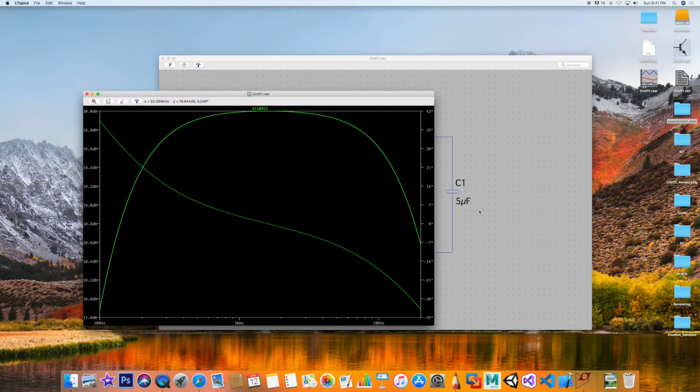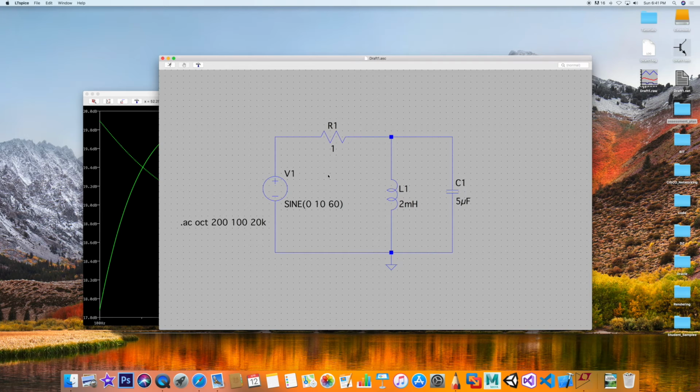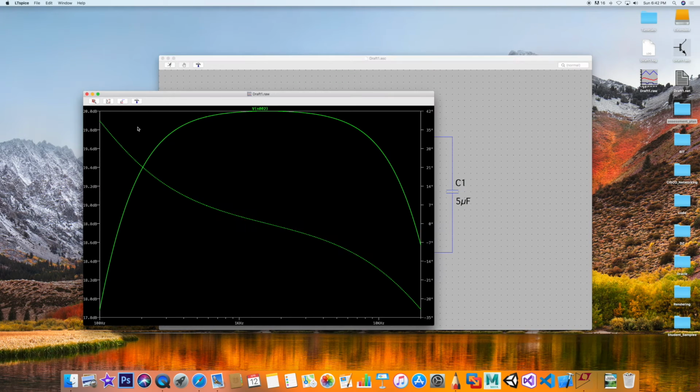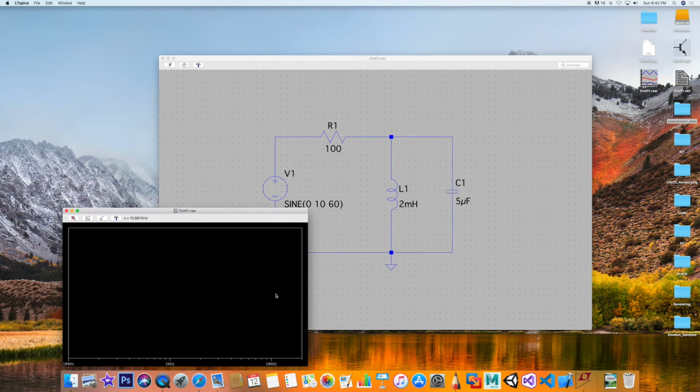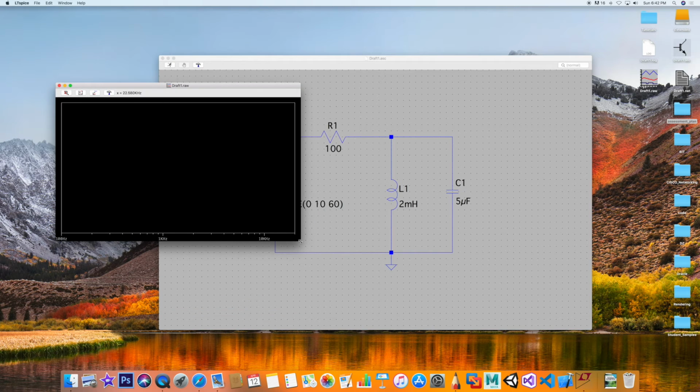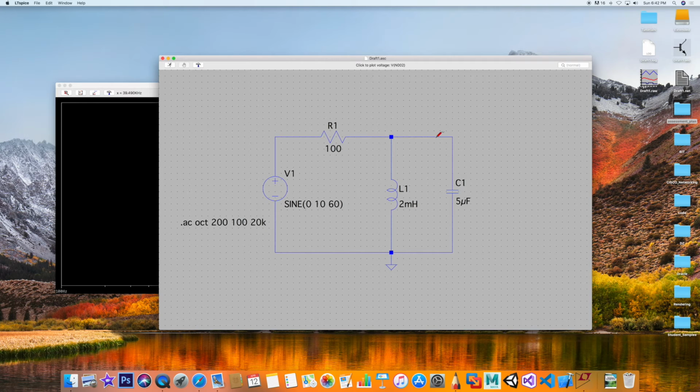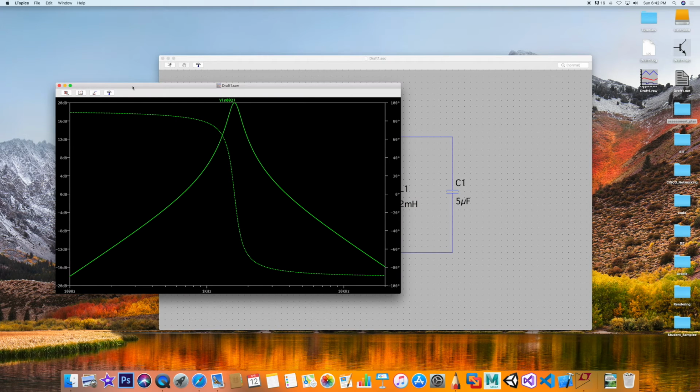Great. So can we narrow this? Can we really narrow this? Sure. Now remember with 10 what we did. So let's go ahead and do a factor of another 10. So 100 this time. And let's look at our graph and see what happens. Okay, so I'm going to run this again. Make this a little bigger. Let's see what it would look like as I sample the output. And there you have it. Okay, so we have a dramatic shift of the angle right here at 0. It's specifically when you reach the peak. That's the resonant frequency for this circuit.